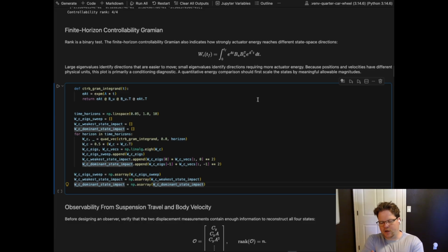One thing to note is that the units are obviously not all consistent. I'm jumping a little bit here, but with the optimization, I am going to go to order one and actually non-dimensionalize things, and that significantly improves the solver results. I don't know why I didn't do that in the last series.